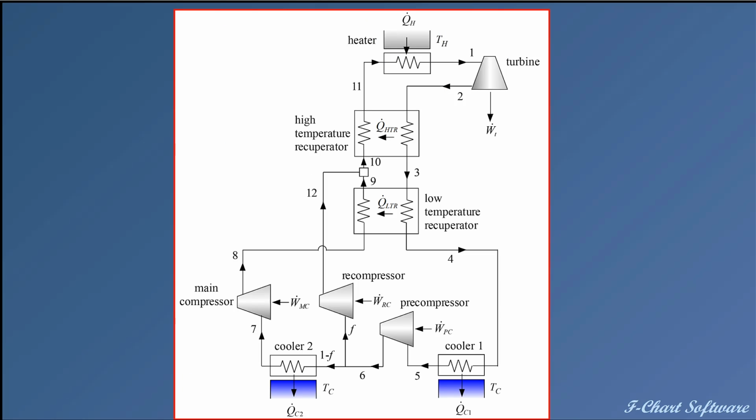So I have one property now, pressure, at every single state point. At this point, I need to pause and think a little bit about how I'm going to tackle this problem. Cycle problems of any complexity are going to ultimately be iterative. And EES is good at that. It can solve large sets of coupled nonlinear equations. But it's going to converge successfully most readily if we're thoughtful about how we enter these equations and how we solve these equations.